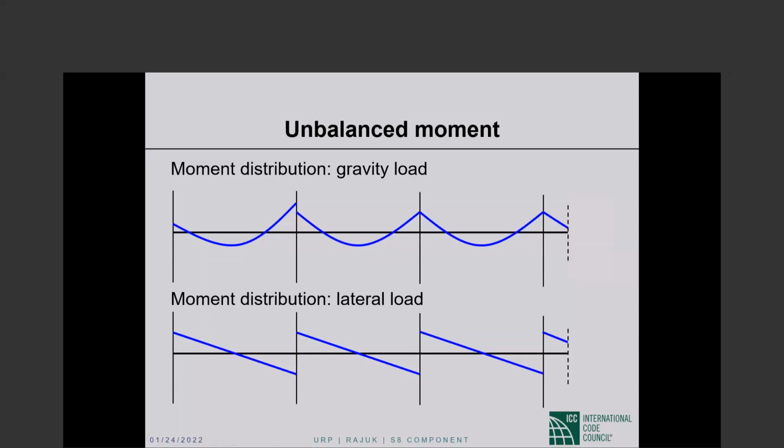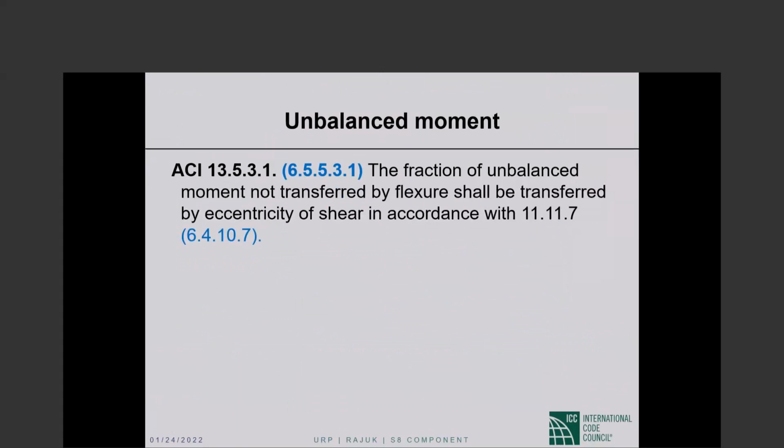This is a huge difference between a flat plate column frame that carries gravity only, and a flat plate column frame that also resists wind and earthquakes. A huge difference when it comes to this unbalanced moment transfer.